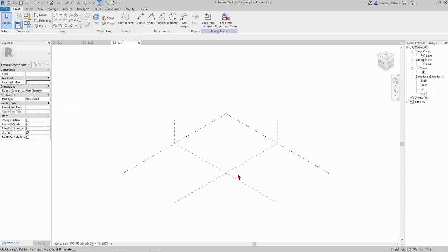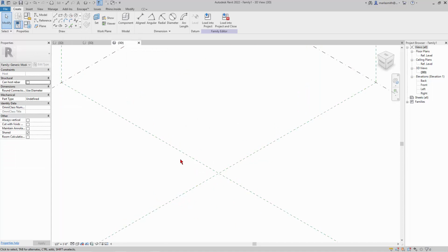And so basically what we need to do here is create 3 points, make them adaptive because that means they'll suck down to other points, and make a face on that and put a surface on it. And put a material on it. So later on we can make thickness and we can do other things, but start simple.